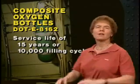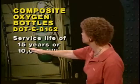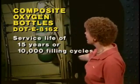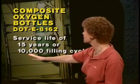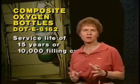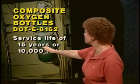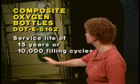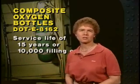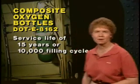The lightweight cylinders have a longer life, 24 years, compared to 15 years for the composite, but the composite bottles have more than double the filling cycles, 10,000. So think of the composite bottles as having lots of nice round numbers: 15 years of service life and 10,000 filling cycles, whichever comes first. Composite oxygen bottles, by the way, are aluminum bottles that are wrapped with Kevlar.